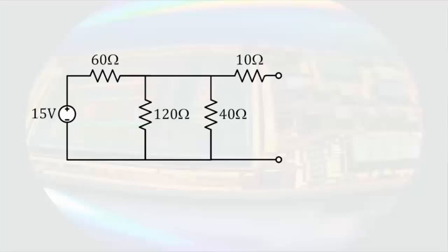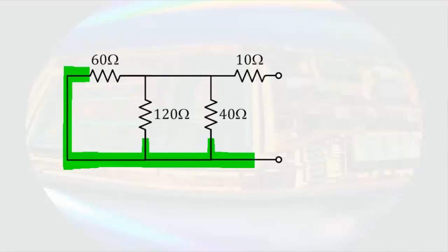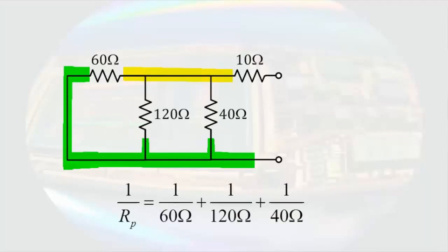One more observation about this circuit. The source in the circuit is an independent voltage source. If we turn the voltage source off, remember that turning a voltage source off results in 0 volts. We have only resistances left in the circuit. We can then combine the resistors. Let's highlight these nodes for clarity. Then we can easily see that the 3 resistors are in parallel and can be combined by adding their conductances. The result is an equivalent resistance of 20 ohms. The 20 ohm resistor then can combine with the 10 ohm resistor, resulting in 30 ohms.